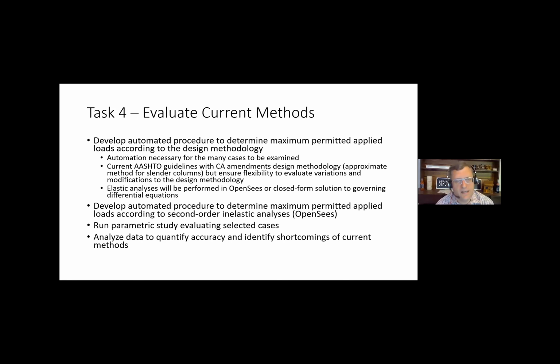Then get into automating all this, look at the many cases that need to be examined, and compare the results with current AASHTO guidelines to ensure flexibility and evaluate different variations and modifications to the design methodology. Then run parametric studies evaluating selected cases and analyze data to quantify the accuracy and identify shortcomings.